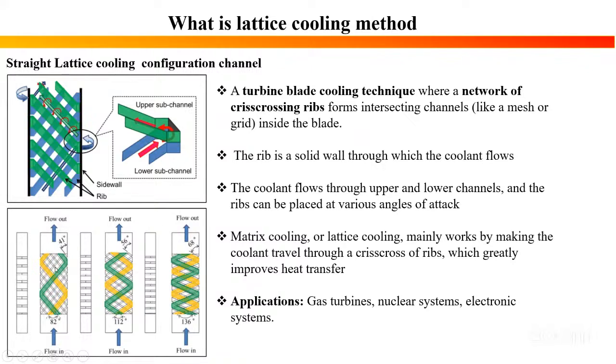Here you can see the straight channel and how we can simulate it at various angles. Right now the inlet flow angle is 136 degrees and the outlet flow angle is 68 degrees. Similarly, you can change the angle of attack and angle of incidence to optimize the heat transfer area and get the results.